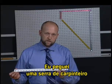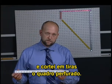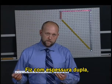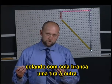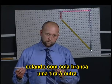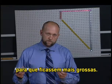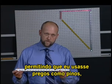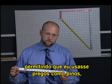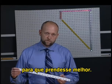So I took a regular carpenter's saw and cut out strips of the pegboard material, and I actually put it together double width. I glued with white glue one strip to another strip to get a little more thickness, and that made the links a little stiffer and also enabled me to use nails as pins so that they would stay in place a little more securely.